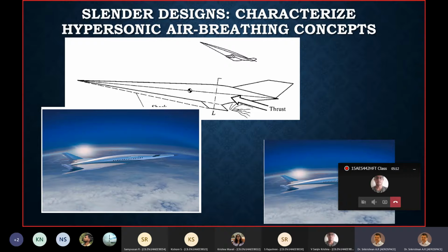So wherever we can approximate the flow deflection to be small, I repeat that, wherever we can approximate the flow deflection and the concomitant velocity variations from the mainstream components to be small relative to the mainstream components, then we have a chance to apply the small disturbance approach or small perturbation theory.